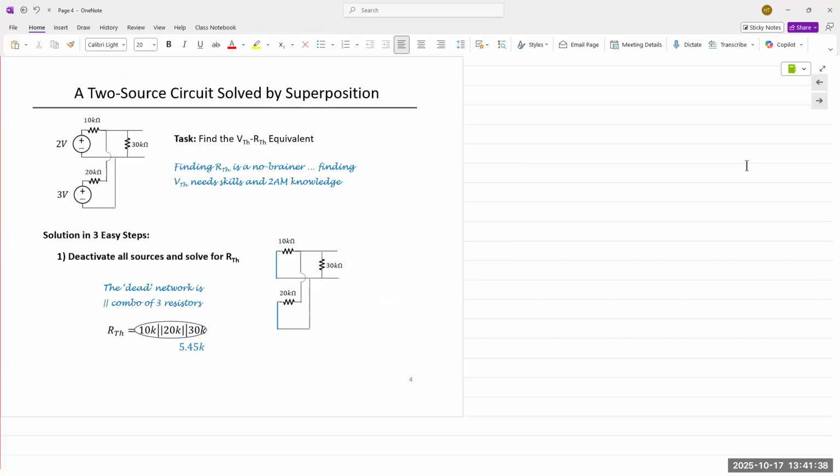You can break it up into multiple parts, analyze the circuit for each individual part, and then calculate the voltages and currents that appear in the circuit due to only one source active at a time. Then if you sum them all up, that would give you the actual voltage and current.